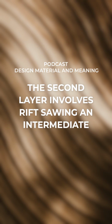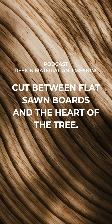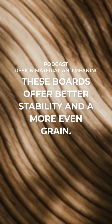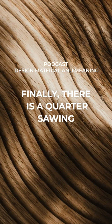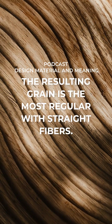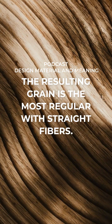The second method involves rift sawing, an intermediate cut between flat sawn boards and the heart of the tree. These boards offer better stability and a more even grain. Finally, there is quarter sawing, which cuts through the heart of the tree. The resulting grain is the most regular, with straight fibers.